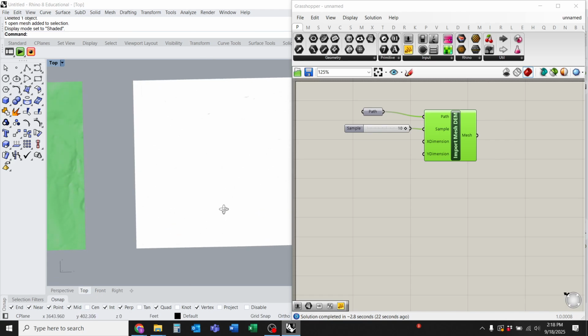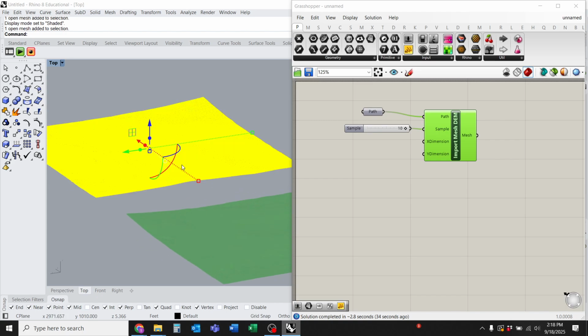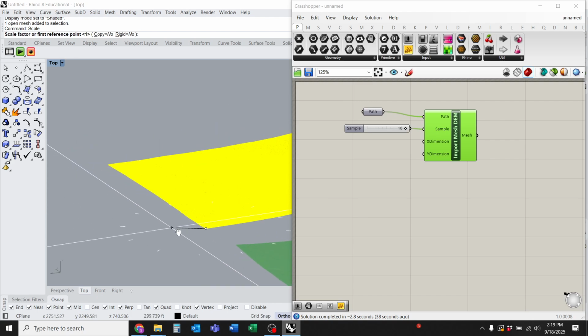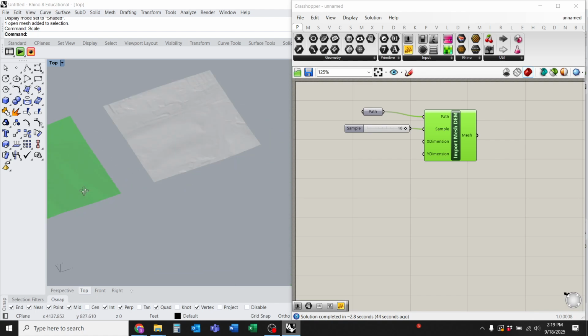now there's not a whole lot of elevation change on this little square, but of course when you get to the mountain portion, there will be. And now you could scale that if you just type in the scale command, click one corner and then the other, and type in 1 km in the command line. That should get you where you need to go.